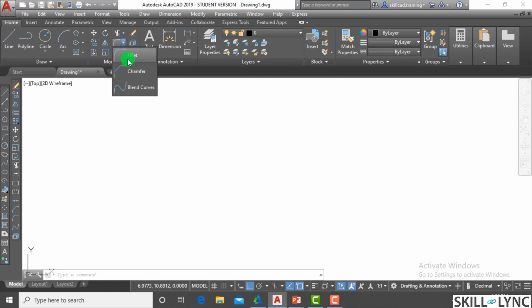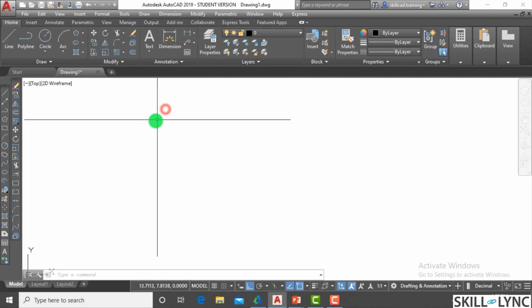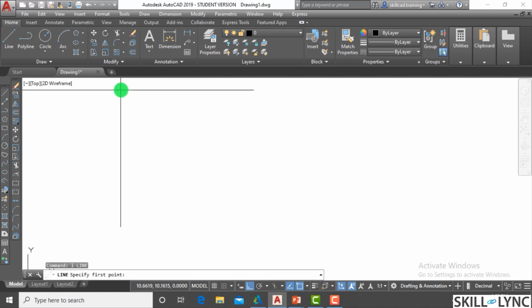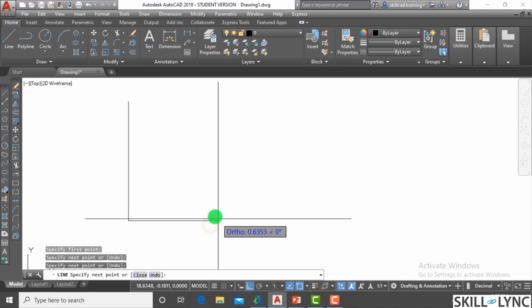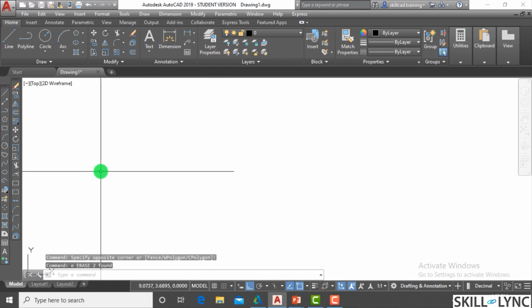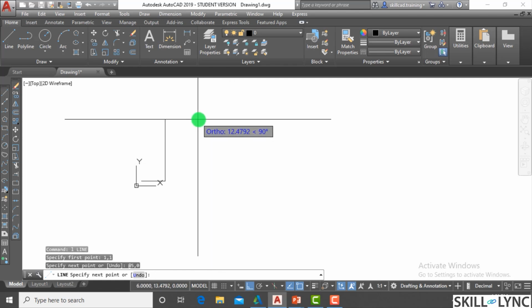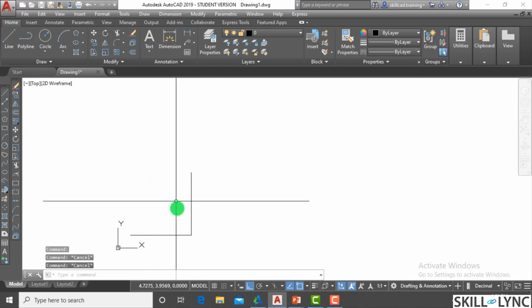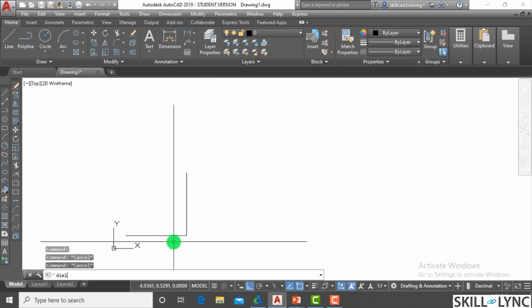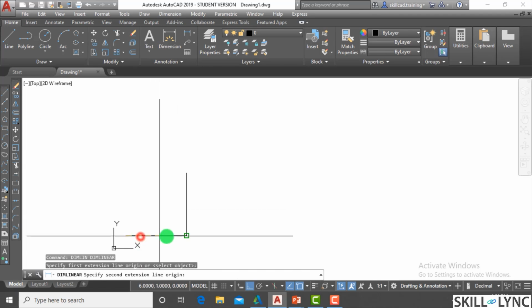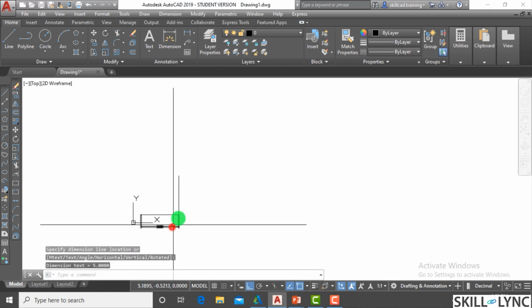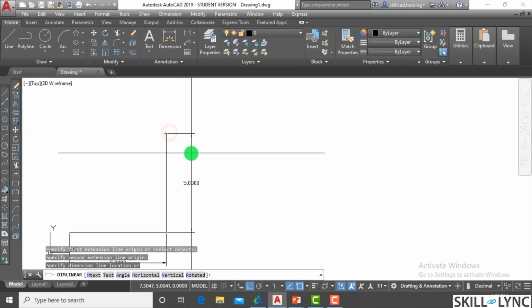So we have a fillet option. You can see there's a curve over here. Let's see how it works. So go for the line option. Let me create a line of a length, say I start from 1,1, and at the rate, let's say 5 units, right? Because you have learned quite well how to create lines by coordinate systems. So you have this line just created. I'm putting a dimension for reference, a 5 unit length here and a 5 unit length here, right?